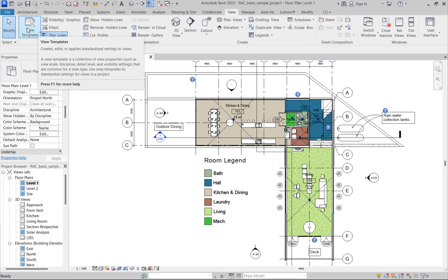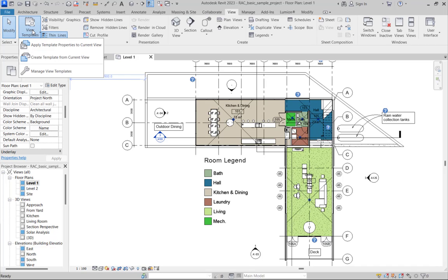But in Autodesk Revit, you can save the view that you want as a view template anytime that you want. Then you can apply the template to your view to get the same view that you want. So this is very good in Autodesk Revit. Aside from that, you can have your presentation here by doing some rendering in the cloud, rendering in the gallery.